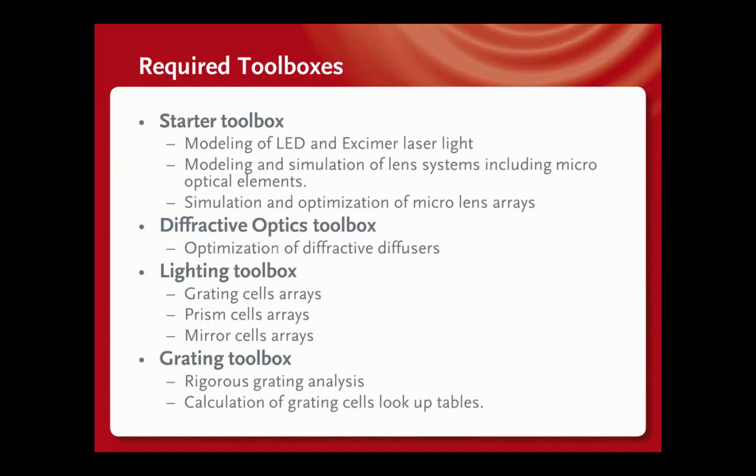So which toolboxes are actually required for the simulation of these different optical setups? With the starter toolbox, you are able to model LED and Excimer laser light, and it is possible to simulate lens systems, including, for example, diffractive optical elements or microlens arrays, or computer-generated holograms or diffractive lenses, and so on.